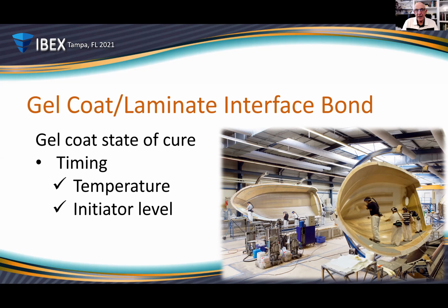And this was a big dollar deal, because what would happen is that these van tops were all painted the same color as the vans. So they were shipped with a primer gel coat, and then they would be painted by the van converter. So now you got a big deal. Now you've got this top that's got cracks. It needs a gel coat repair, and the paint has to be matched. The whole thing has to be repainted. Lots of dollars floating around here on this particular issue that was happening.